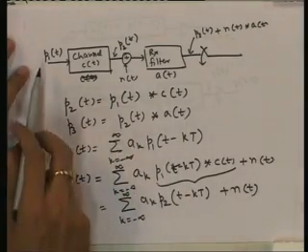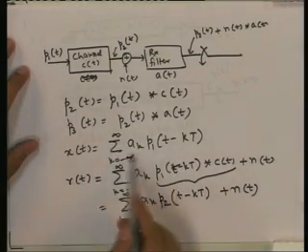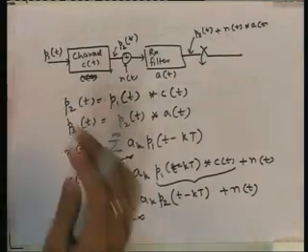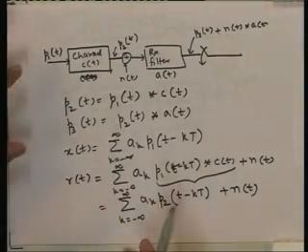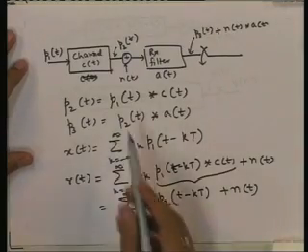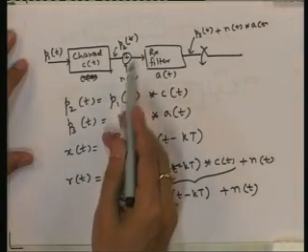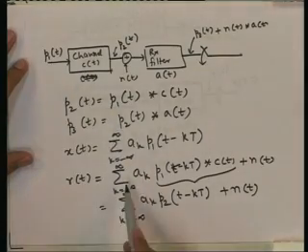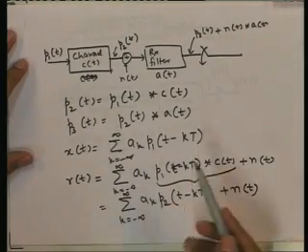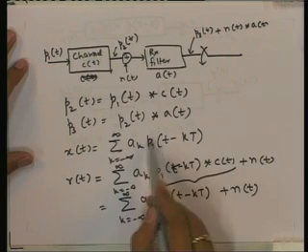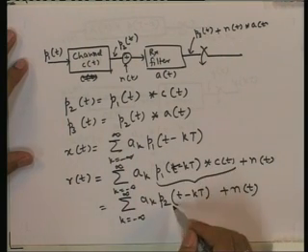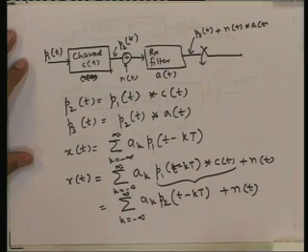Now the actual transmitted signal is this summation of so many shifted pulses after scaling. So when you do this convolution, what we receive here is this noise plus what we transmit here convolved with c(t). That convolution with c(t) can be taken inside the summation, and then the individual convolution can be written as p2 shifted by kT.